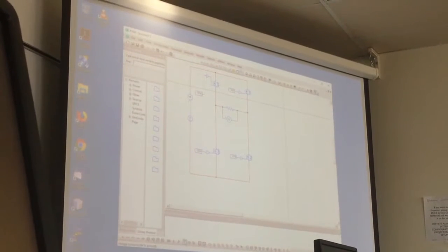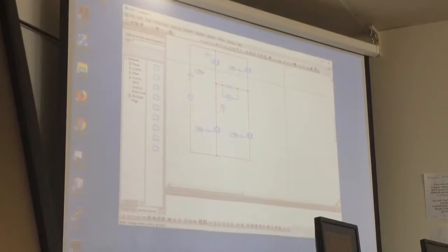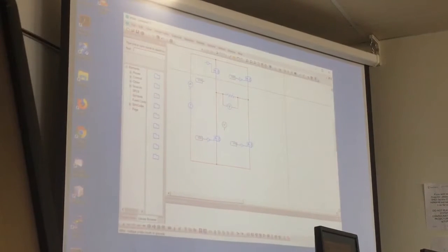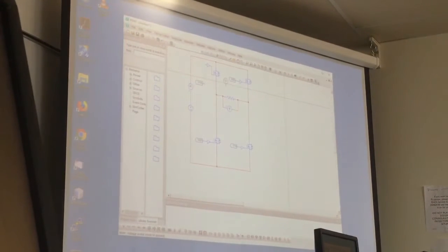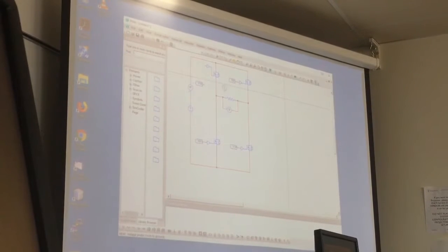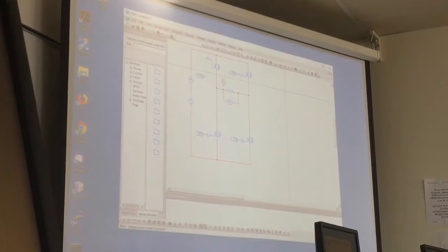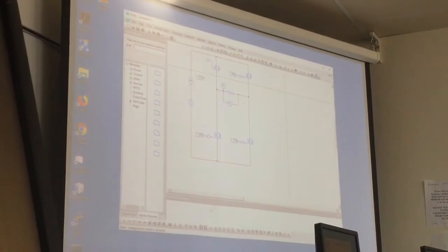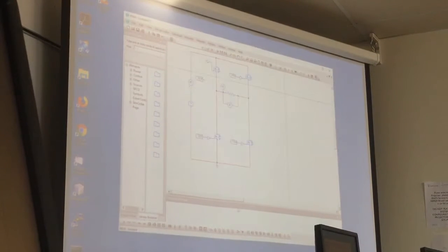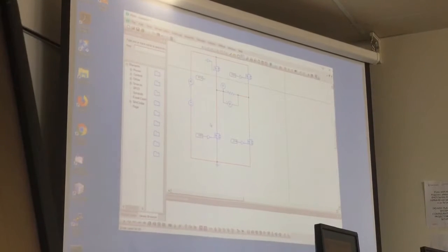Also, we have another option. We have this voltage probe that's going to measure from the point you want to see to the ground. Let's say I'm connecting these to the same point here, but then I have my ground. Where's my ground? My ground's here, okay? I'll connect my ground here. Then this probe will measure the voltage between this point and the ground. So we'll be measuring the voltage on this MOSFET.